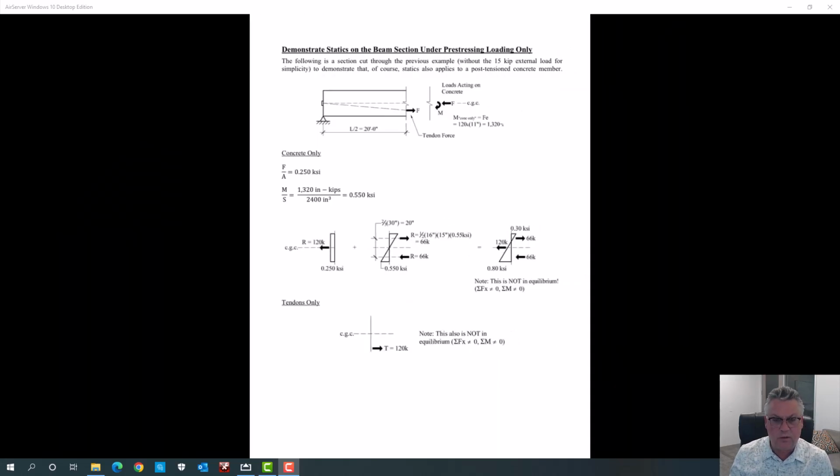That's what T.Y. Lin was doing for us. He was fixing a problem. That problem was that while it was analytically possible to design pre-stressed concrete, it was realistically impossible. Once he showed us that we can take the tendons out and put loads in their place and analyze the system and get the same answers, then pre-stressed concrete became available to everybody.